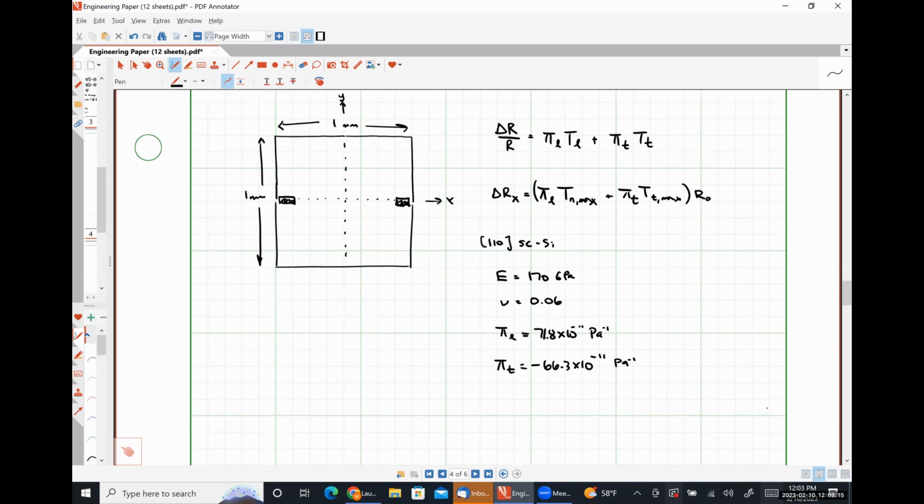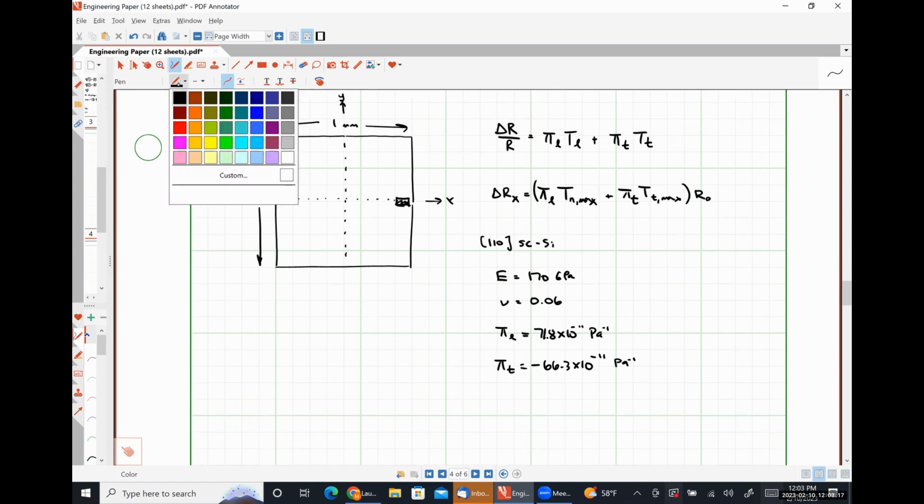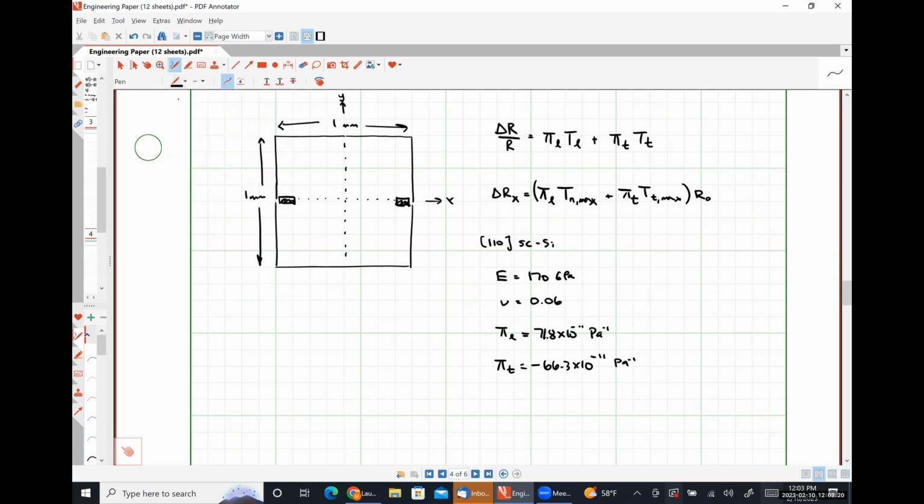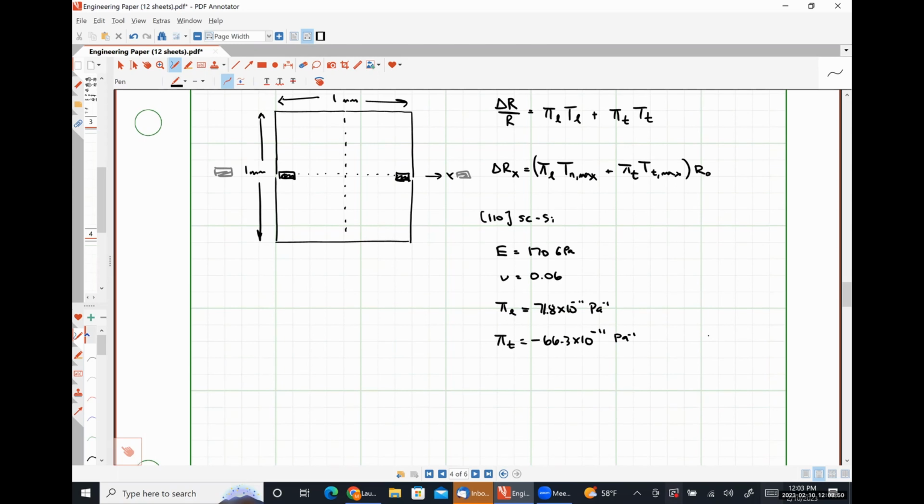Okay. And what I'm going to do now also is I'm going to put two more piezoresistors here. Let's do these in gray. And I'll put one over here and one over here. So they are outside of the diaphragm. The reason they're outside of the diaphragm is so that they do not undergo any stress, so that their resistance value is effectively fixed. If I have 4 resistors, I can then utilize a Wheatstone bridge configuration where I'll have something like this.